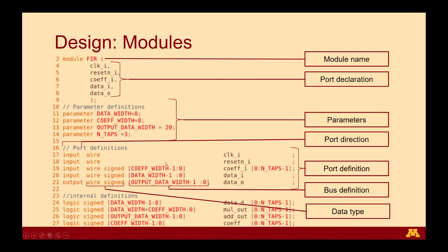Everything to the left of your signal definition is called a packed array. Packed arrays in general define physical quantities such as buses or memories, whereas the quantities on the right, the unpacked elements, represent more of a number.